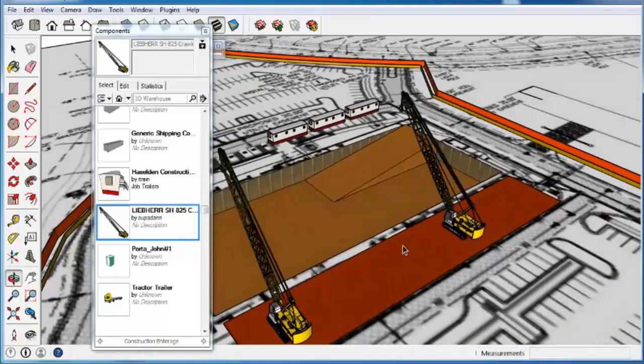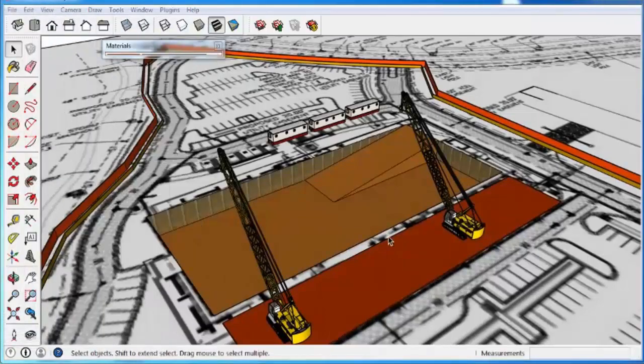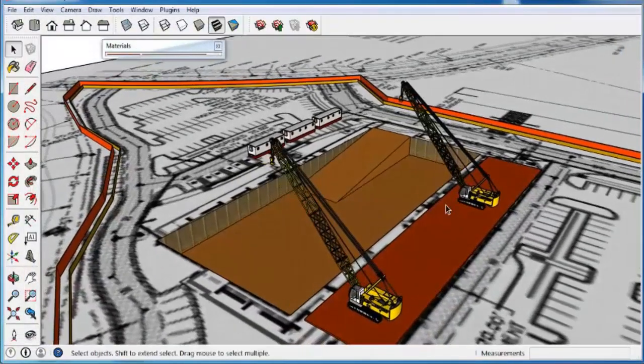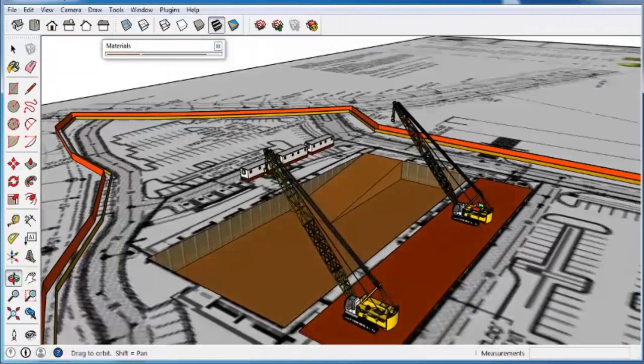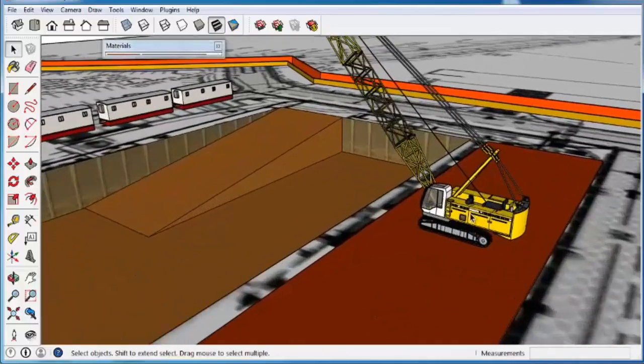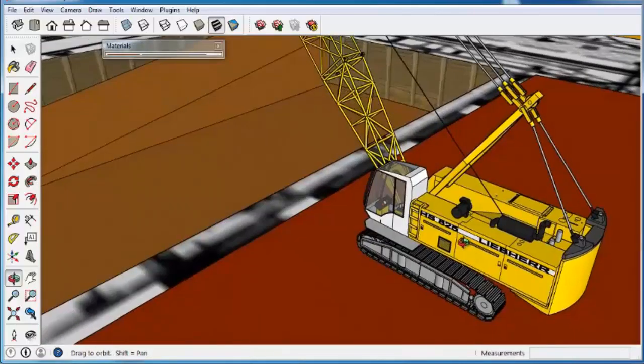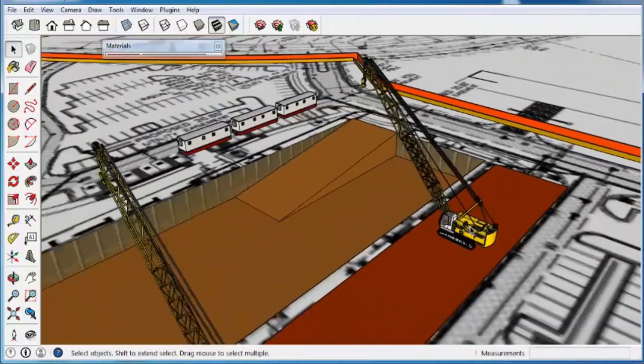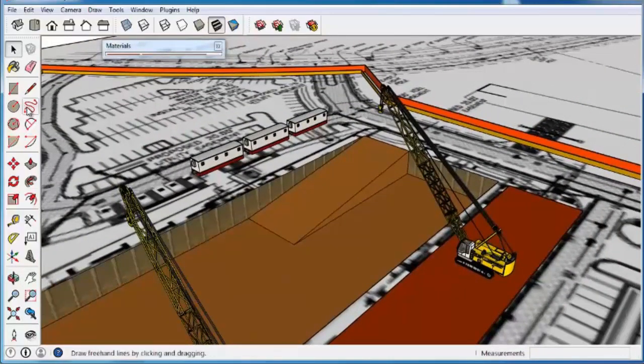One thing that we often see when people are building these types of logistical site plans is they actually use some of the components in here to help them figure out things like the crane radiuses and safety zones and so forth. You can come in here, and if you download a crane that you like or that you want to use, just be aware that you're able to come in here and actually modify it to whatever size you need. So these are fully editable, but one thing that we often see is they use these cranes to better show the radius that they can affect.